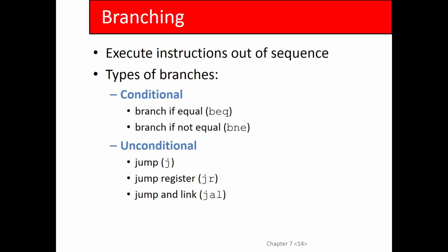And then you've got branching, which is how you implement constructs like if statements and loops. So there are branches and jumps. There's a little bit of weird terminology here, by the way. A branch and a jump do the same thing. They interrupt program flow. Instead of going one instruction after the next, a branch or a jump interrupts the normal counting sequence of the program counter. It allows you to jump ahead or jump backwards, right? So why are they named differently?